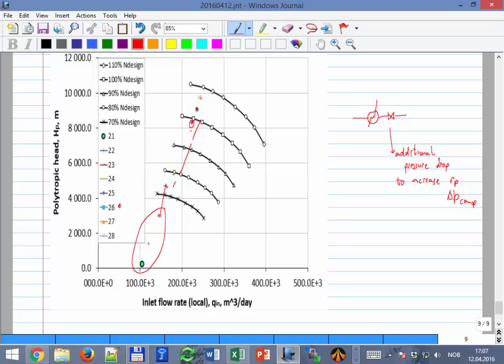Okay? So the main verification that you have to make is that the points fall on the diagram, inside the diagram, and in this case we see it works quite okay for all the points. The only issue is these points, the first 3 years, and we see that the conclusion is that we have to put an inlet valve. Here we have the scrubber, and here we have our compressor. Additional valve is almost like a choke.